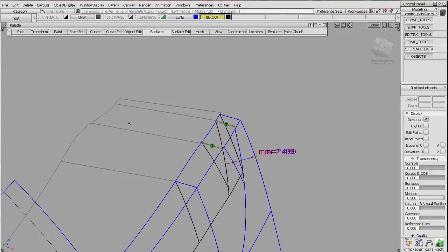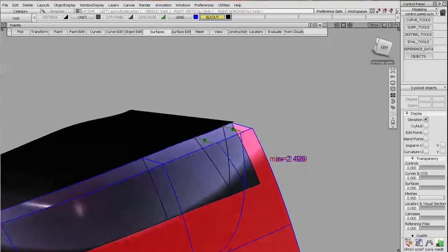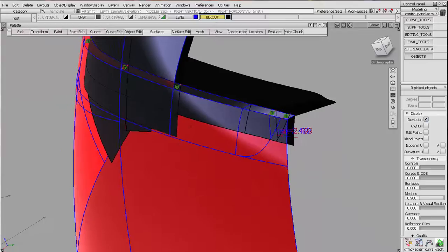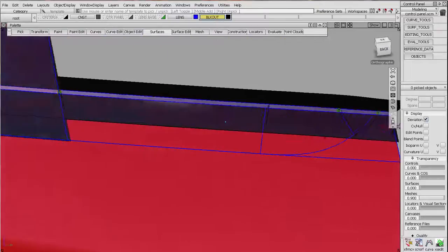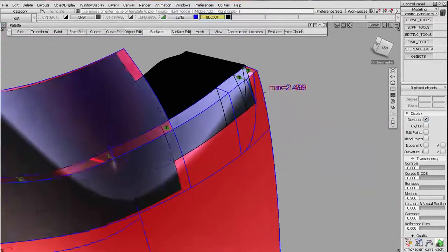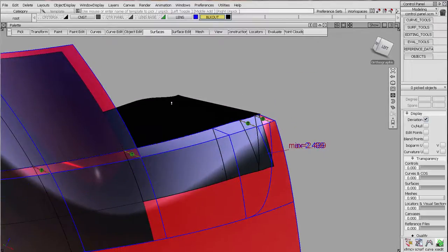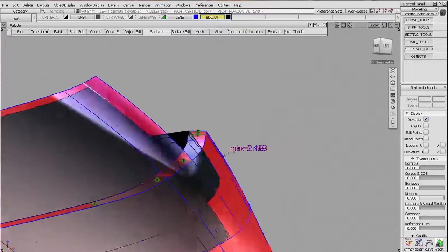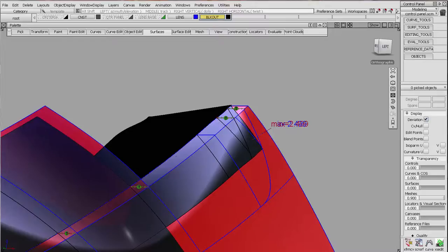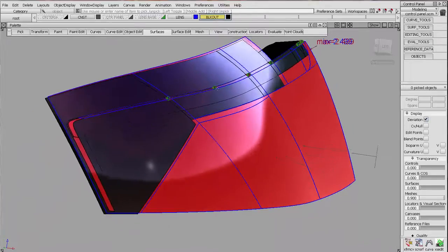If we pick template and pick this, toggle template, and then do my hardware shading, that is what the edge of that lamp should look like. We have 10 millimeters of blackout, lens offset 2.5 millimeters plus 1 millimeter underflush with a 3-degree draft surface on the top. I'm going to go through and trim the rest of this up, and we'll move on.